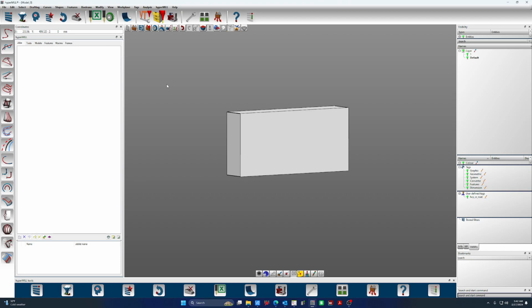So we're basically going to take our CAD model, put it in the file where we would like to have all the data go, and then path all our CAM data to that same file so everything stays together, which means when we open it up on different workstations, or we send the file off to support, or we're one of the few people that have decided to work on a server, we have our toolpath data already generated, stock models and everything are happy. The CAM file can find all of that data easily.